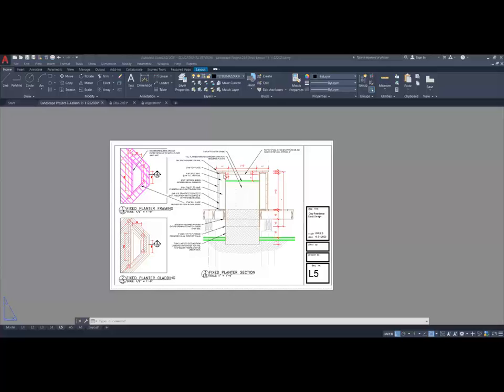And then the section I figured I would make at a larger scale, 1-inch scale, so then I can get lots of details and notes into one drawing without having multiple drawings here. So it's fairly simple and straightforward. I've also indicated in here the 4-foot sheet of plywood as a separate piece or a separate dimension because all the other ones more or less give all the details that are required. A lot of this is existing. We can't really change or modify, but the 4-foot sheet of plywood is a critical dimension because you're trying to identify, don't cut the plywood, make sure that you got the 4-foot lengths. Everything else is sort of either there already or has very little adjustment to it.